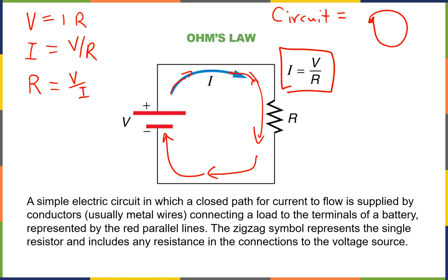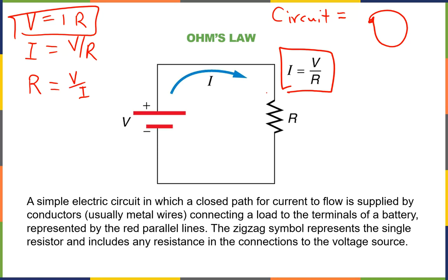Now, when we use Ohm's Law, it's specific to a resistor, and what this equation really says is the voltage drop across the resistor. Remember, voltage, that's the energy per charge. So the voltage drop is how much the potential energy drops per charge, or how much energy you gave away per charge through that resistor. So the voltage from that equation is the difference between the voltage on the side the current went in.